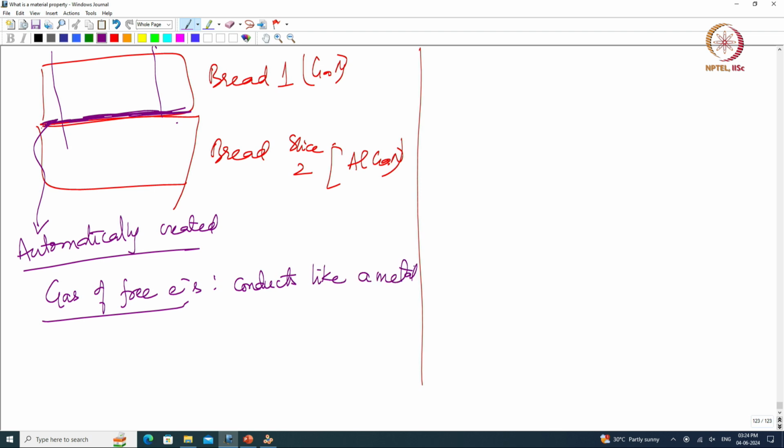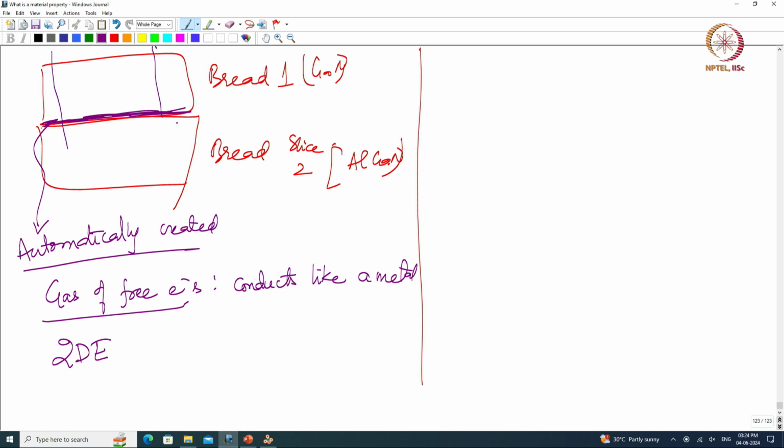Okay. So, this is what is called 2D, and it is just two dimensional, right, just at the interface. Actually, this is real 2D, right. It exists atomic layer thick, and it is only at the interface between aluminum gallium nitride and gallium nitride, right. So, this is what is called 2D electron gas. How did we generate this? We generated this by just combining two materials with different polarizations, that is it, two Wurtzite materials with different polarizations.